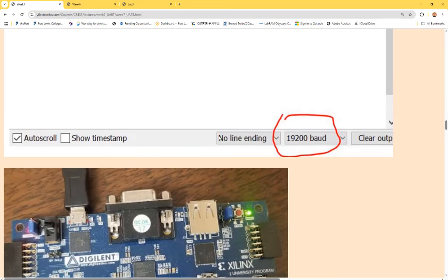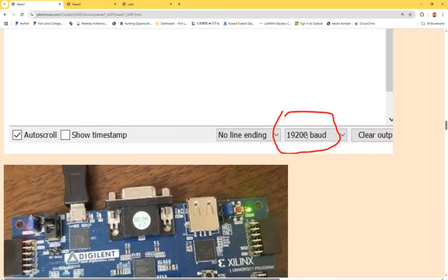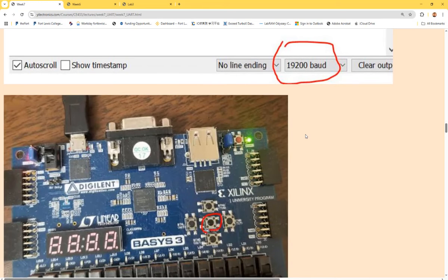And also the baud rate. Should you use 9600 or should you use 19200? Which one should you use? Definitely this one because it's already being overwritten, right? So even though some module has 9600, it's being overwritten. So this is the correct one that you should use. Okay?